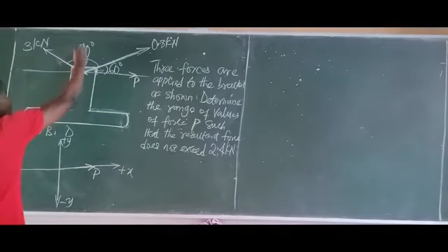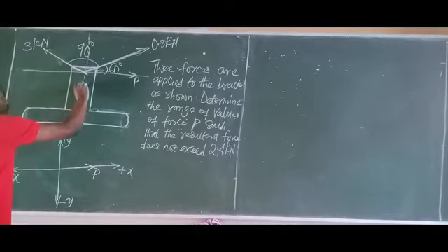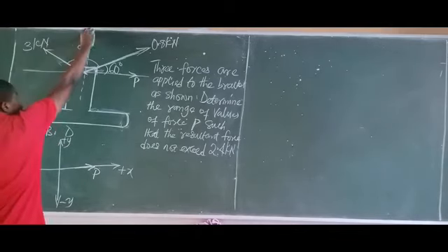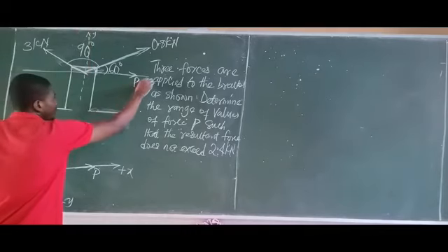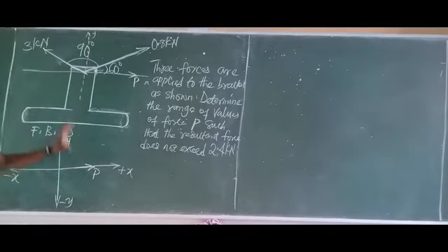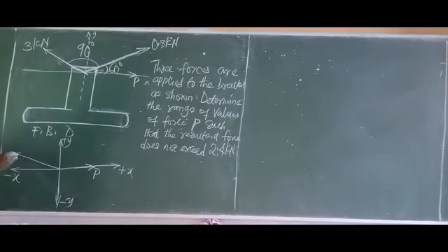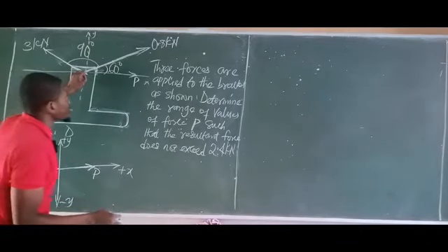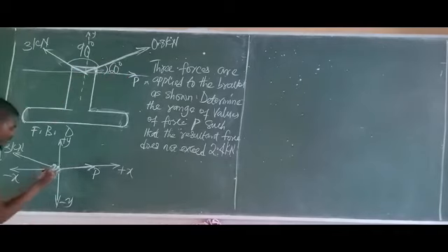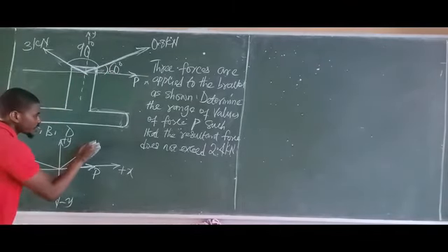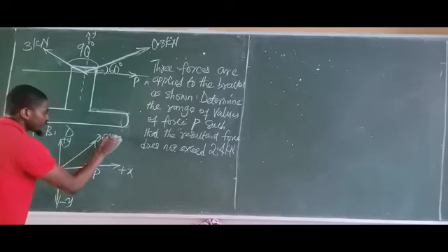So if I draw an imaginary line here, you can see that this automatically becomes my y-axis, and this becomes my x-axis. Which is what I am doing here, representing this information on the free body diagram. Now remember, from the origin we have a force of 3 kilonewtons. So you also represent it here, a force of 3 kilonewtons from the origin pointing out. And then we have a force of 0.8 kilonewtons from the origin pointing this other way. It's as simple as this.